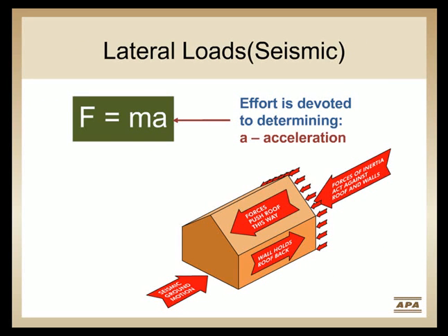For our lateral loads regarding seismic or earthquake, that force is equal to the ground acceleration due to the earthquake times the building mass. So again, your choice in building materials is going to impact the force you have to resist. The more mass of your structure, the larger the force. And so when we are considering wood frame construction, this is important to remember.